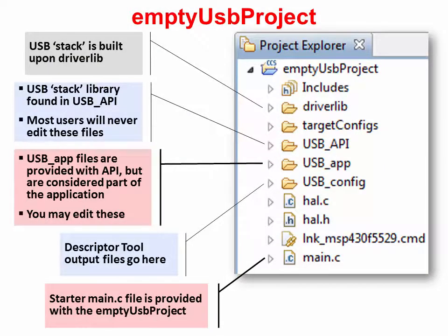Can we really call this an empty project? The MSP430 apps team has already included all of the pieces we need for a USB software design. From the top, the driver library in gray has already been included for us. Likewise, the USB stack is already there too in a folder called USB_API. We've used the blue background here to show that you shouldn't need to edit these files.